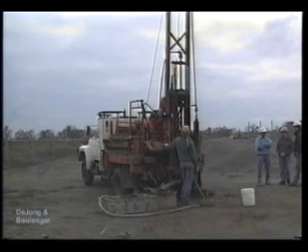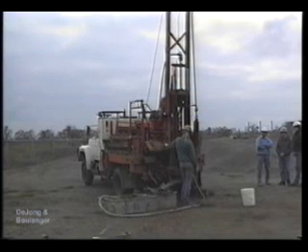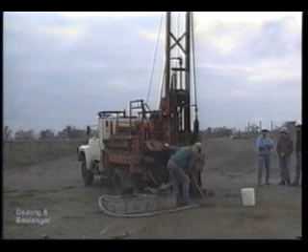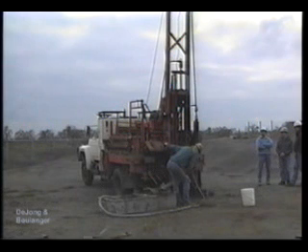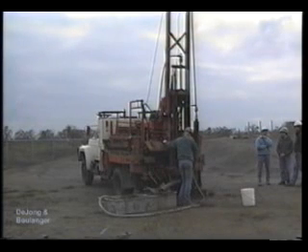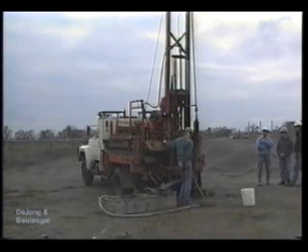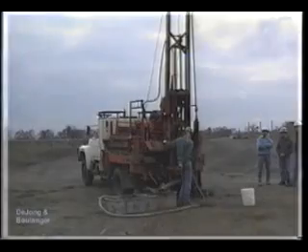Rock cores can be heavily fractured and damaged by the coring process. Failure to distinguish between natural and drilling-induced fractures on the drilling logs can lead to a completely erroneous interpretation of a rock mass's characteristics. Alteration to the drilling equipment and procedures can significantly improve the core quality and percent recovery in many situations, and these changes should be recorded on the drilling logs.